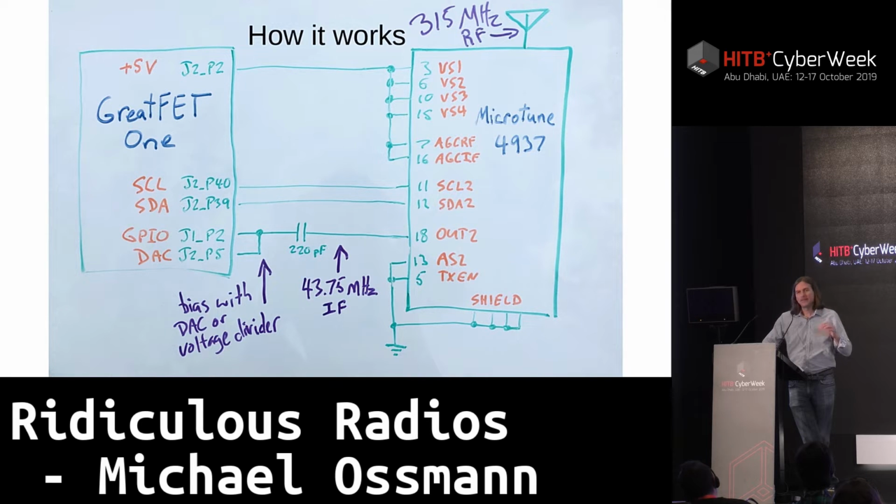And so in this case, we wanted to make sure that we could get the GPIO pin to trigger. Now, a general purpose IO pin has some voltage threshold. You have to exceed some upper threshold in order to flip it to a 1. And then you have to drop the voltage below some lower threshold in order to flip that input to a 0. And those thresholds aren't exactly the same point. There's some distance apart on the voltage scale, some amount of voltage that you have to exceed in order to get this bit to flip repeatedly.